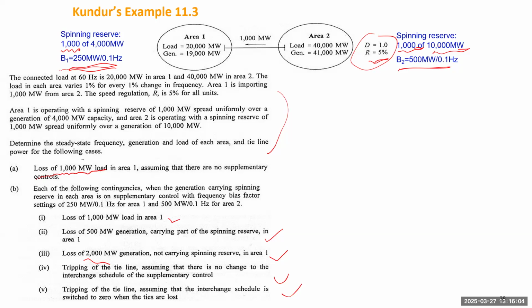For instance, my ACE wants to maintain the frequency deviation of this area, also tie line flow to my neighbors, but I don't know there's a contingency on the tie line. But if that tie line is already out, already disconnected, why do I want to maintain tie line flow? I can simply cross off the item in my ACE. I only maintain my frequency, or maybe the new tie line flow from another neighbor. So you can always do that. So the last two questions just check whether you keep the same ACE or you update ACE.